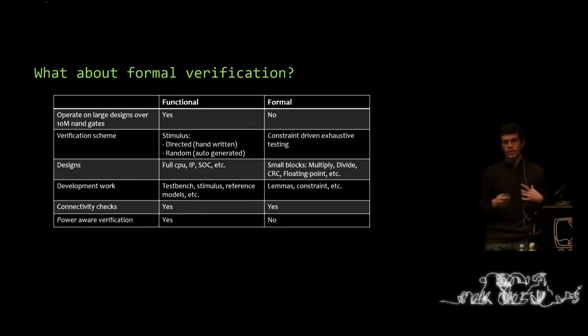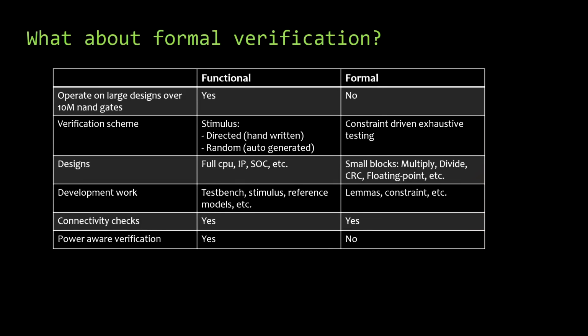Now, one question that I often get asked, or a myth that I sometimes see, is, what about formal verification and formal methods? If anyone's not familiar, formal methods is basically a mathematical proof of the behavior of a certain design. And formal verification is great for some things. It's really cool to get a proof that says 100% this is how it worked. The problem is, first off, formal tools really struggle when you give them a big design. They're basically SAT solvers. They can't deal with that.